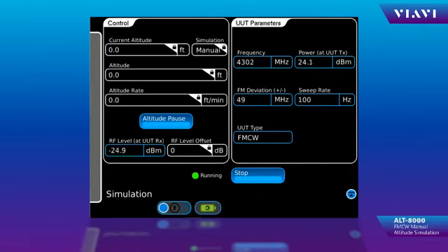If all UUT parametrics are within tolerance and the correct altitude is displayed in the cockpit, the rad-out under test is functional. If the UUT parametrics are good and the indication does not display 0 feet in the cockpit, you could have a receive problem. At that point, you could add more power to the RF level offset to determine if you have attenuation in your coaxes.